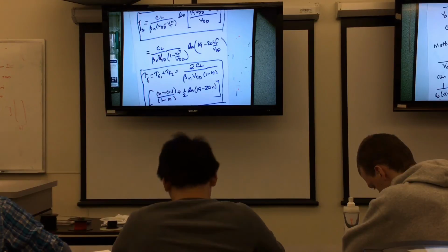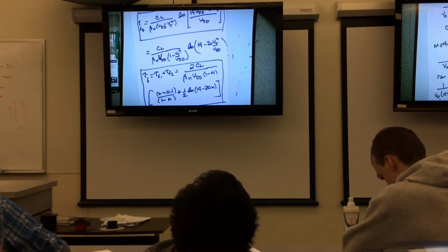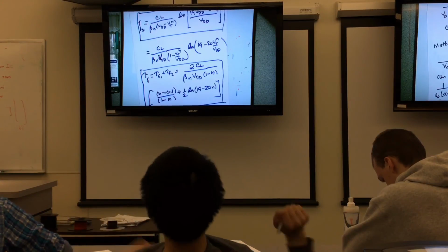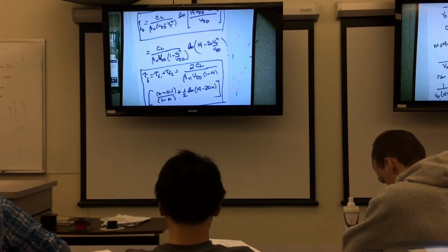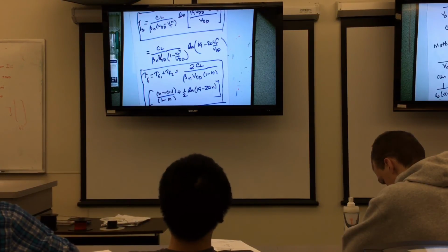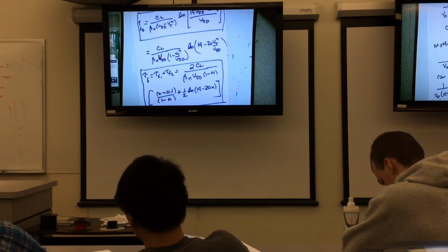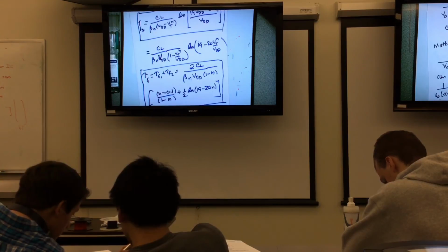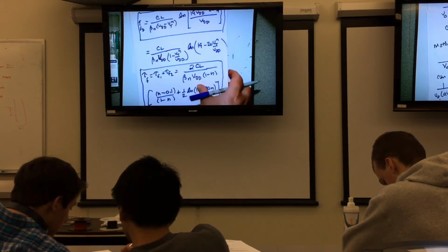If an oxide breaks down, I've forgotten what the actual breakdown field strength is, but it's like megavolt per centimeter or something like that, scaled down to the thickness of nanometers. So you have a lot of problems making VDD big if you wanted to do it. And if you did, you're going to get more power in CMOS.